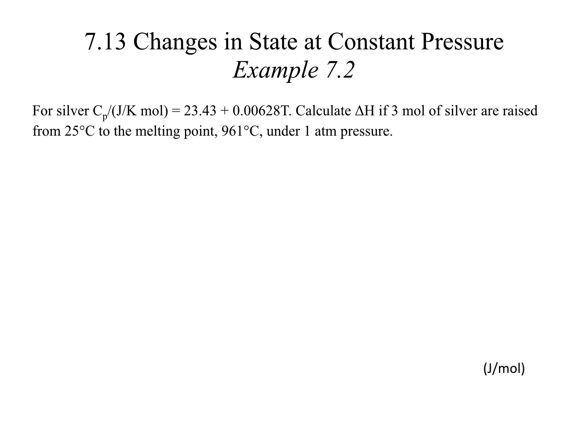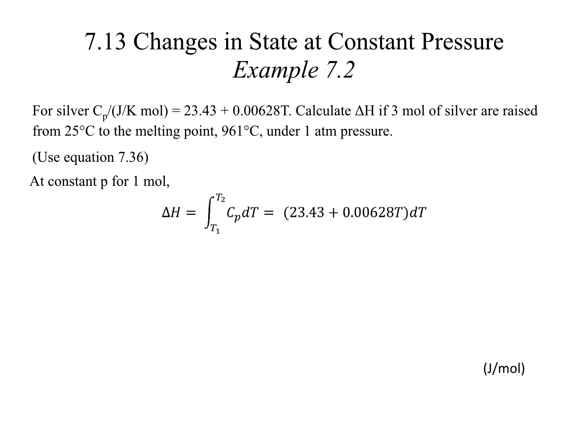Instead of constant volume we have constant pressure conditions, and instead of Cp being a constant we have Cp as a function of temperature explicitly given to us. So using the same equation now, integral Cp dT instead of Cv dT, from temperature T1 to temperature T2. Instead of delta U you have delta H because this is a constant pressure process.